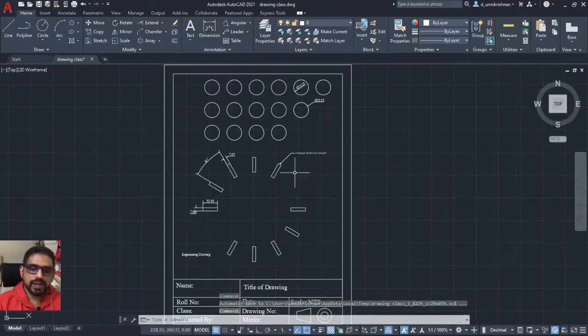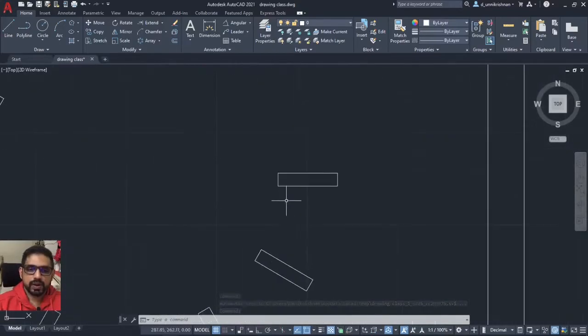Suppose I would like to define one particular rectangle, this rectangle here, to be hidden edge, that is type E line. How do I do it? I do not have that line readily available when I use my line command or a rectangle command. So how do I change it? Now to change it, select the entity.